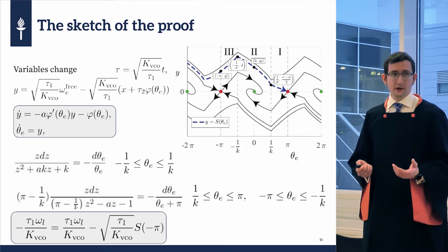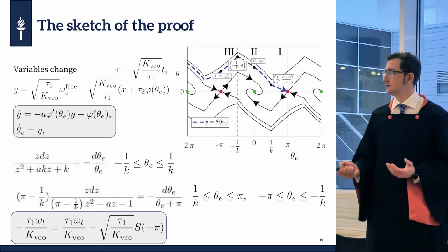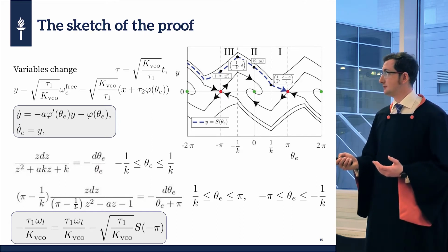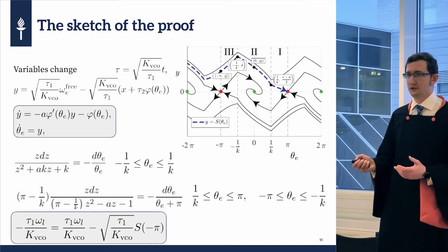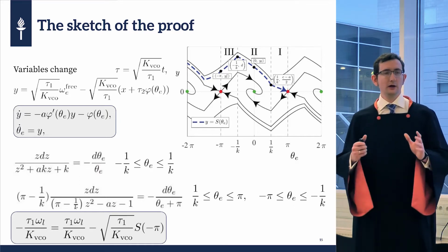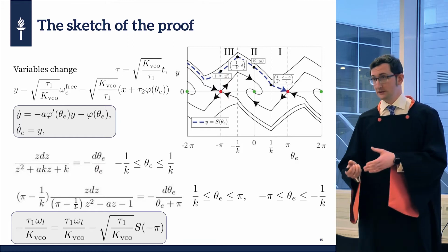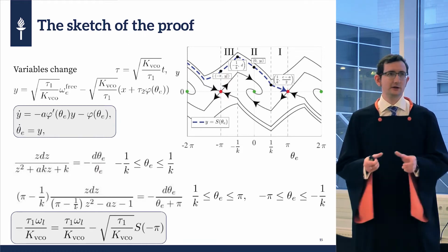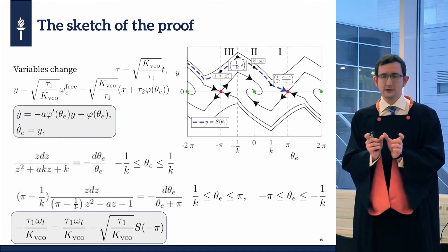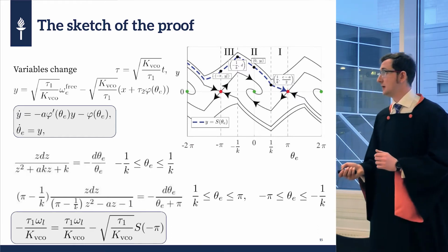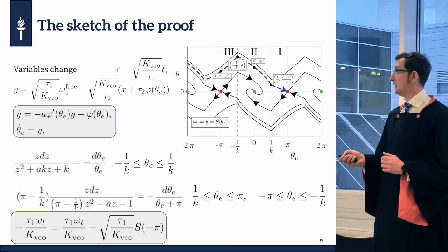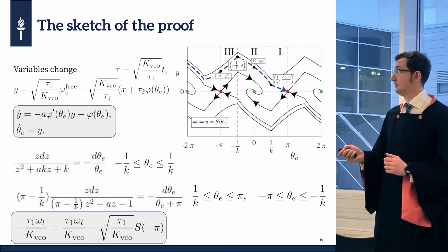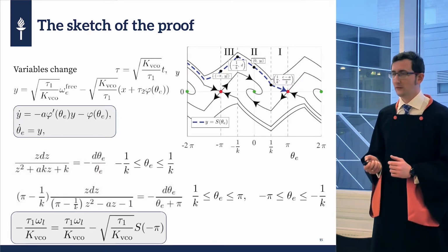First of all, we have to somehow transform the system, do some nonlinear variable change, and then divide equations one by another, which allows this system to be integrated, as the phase detector characteristic is piecewise linear. So we can integrate it on linear pieces and then describe the separatrix behavior. We're actually interested in the ordinate at this point.